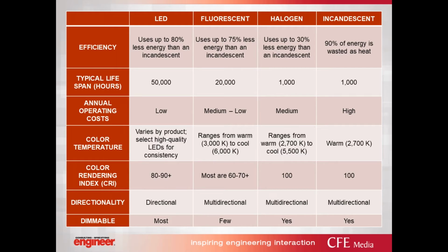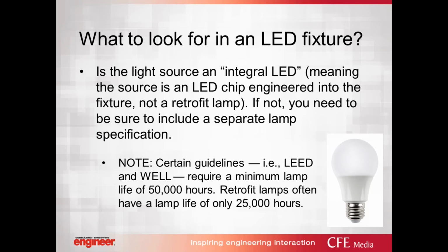Fluorescent, halogen, incandescent are dimmable, or halogen and incandescent are commonly dimmable. Some fluorescents are, most LEDs are. So there are a lot of protocols out there, something that is a coordination nightmare in a lot of projects. But there are certainly dimmable ways for LEDs. It's a matter of coordination with the actual control system in your project.